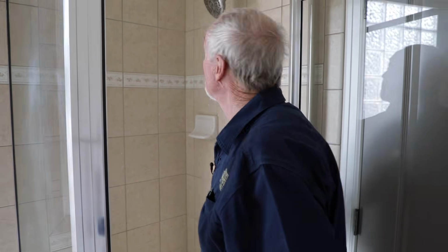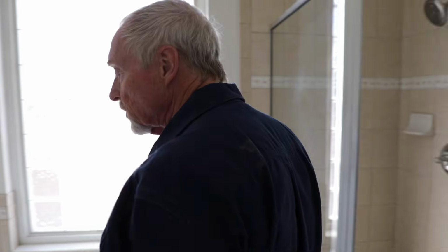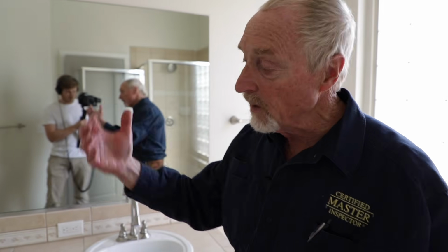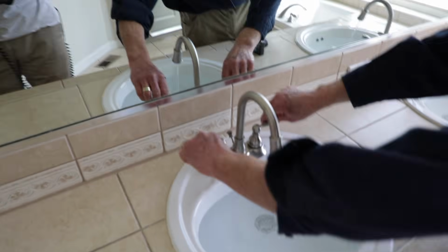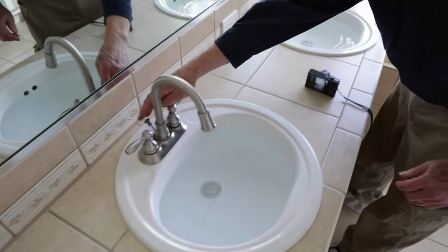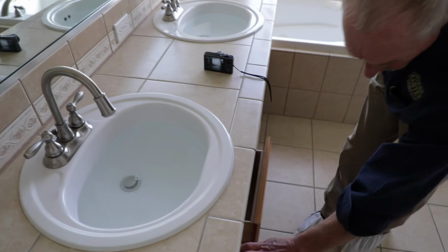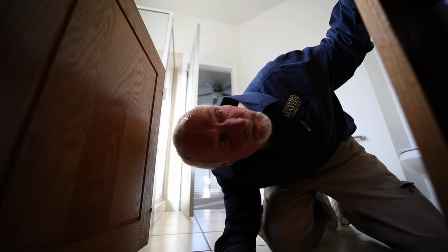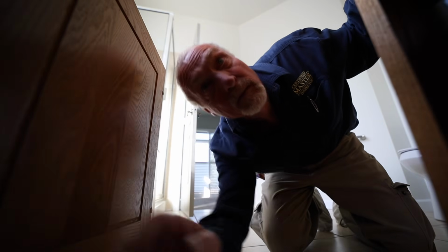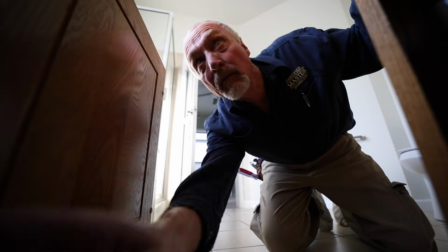Very good. One thing you can also do, you can check the temperature of the water coming out of the water heater. If the temperature coming out of the water heater is under 120 degrees, you know you're going to be good at all your fixtures in the house. And you're out of the gate going to be good there. So we got our sinks filled to the overflows. We'll shut them off. Open this one up here and see if we have anything going on. Nope, looks good. Valves, everything looks good there, no leakage.